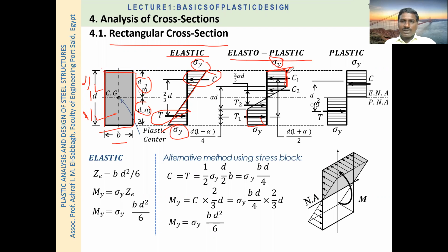Here again, this is the compressive zone and this is the tensile zone. In the elastoplastic behavior, whatever part has the linear line is elastic and the other part is plastic. So this is the elastoplastic zone, and last is the plastic zone. Here stress is constant and there is no elasticity, only elongation with increasing strain.